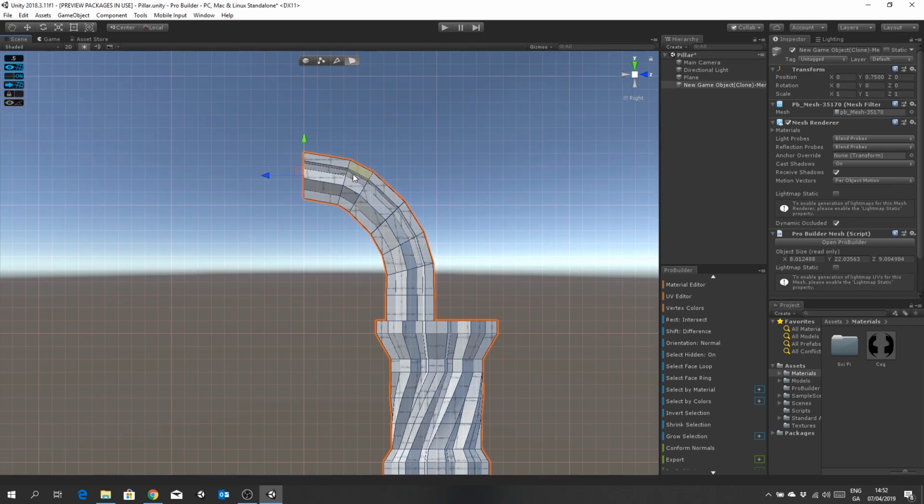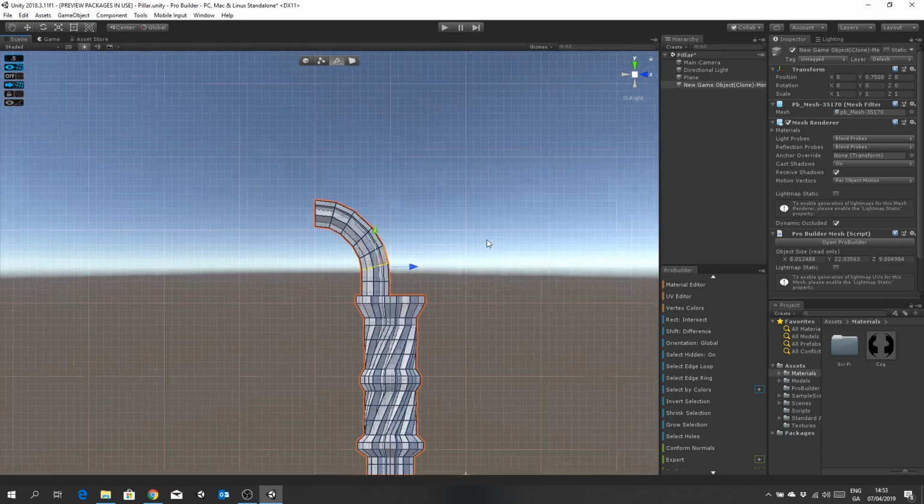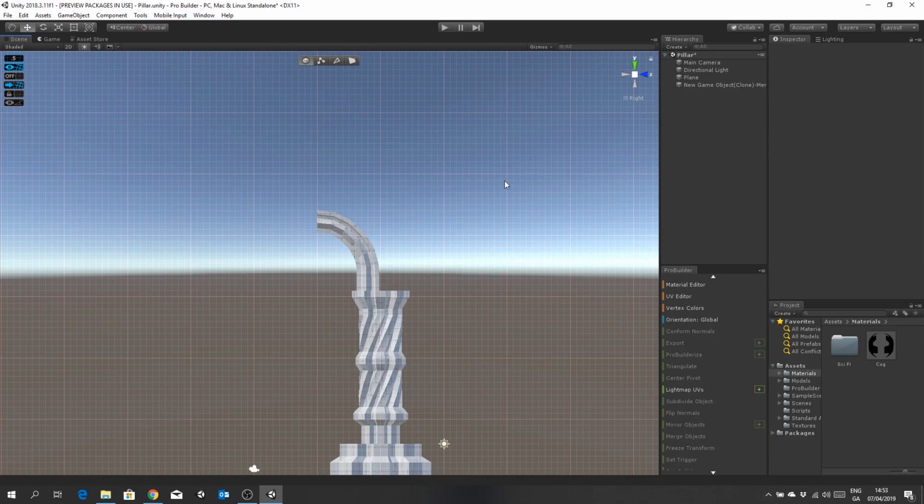And this particular edge loop, something funny went on there. So I'm going to select that edge loop. So is it edge loop? It is, yeah. And I'm going to just do this by eye. So I'll switch ProGrids off, and I'm going to change my orientation. There we go. And let's move that up to about there. That's kind of alright. This one here, I'm always tempted just to move the verts, but something's saying no. So I'll select the edge loop and let's shift that a little bit over. Kind of straighten up that curve. That's pretty cool. Alright. So once again, let's save.